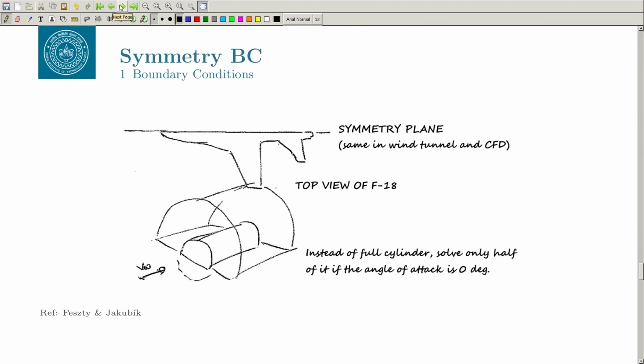Next is the symmetry boundary condition. As I told you, I gave you an example of a channel, but here you can see that let us say you have a flow over an aircraft and you are looking for basically a mean flow, which is symmetric to this airplane. So, for example, the plane is something like this, okay, which is completely symmetric to what we have here, okay. So, something like this, okay. And the flow is completely symmetric to this, the mean flow at least, okay.